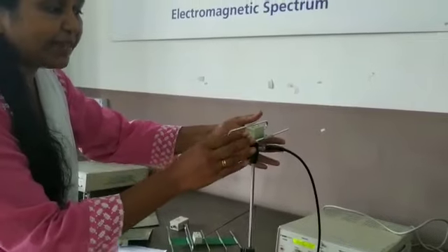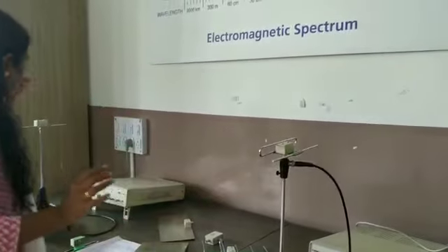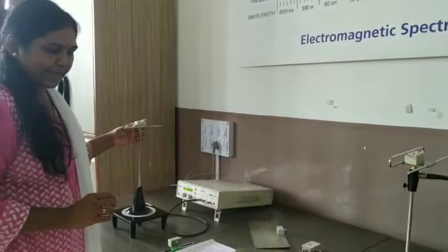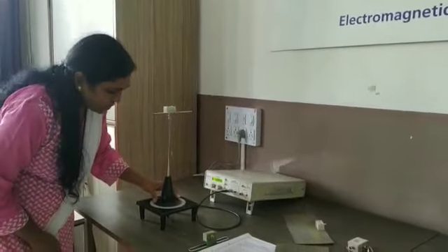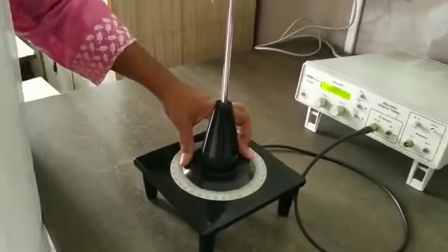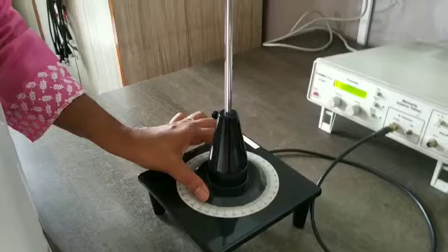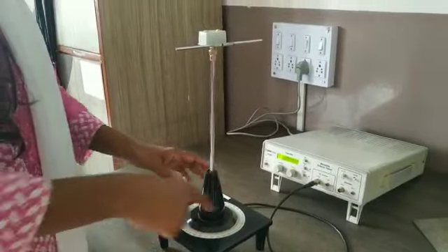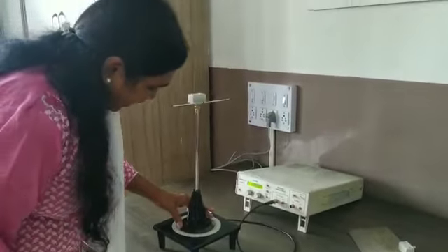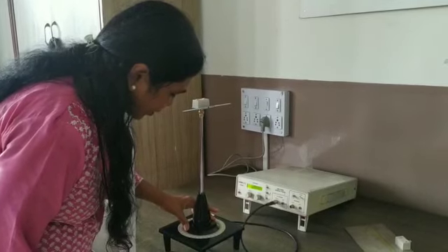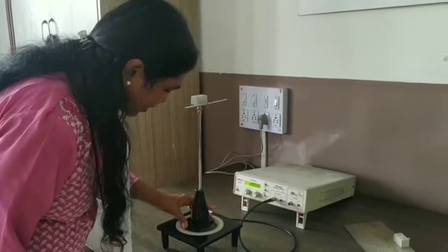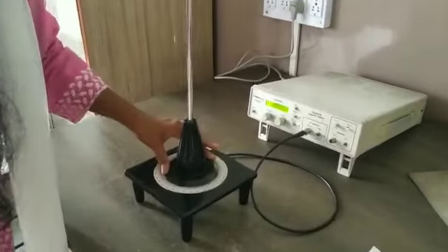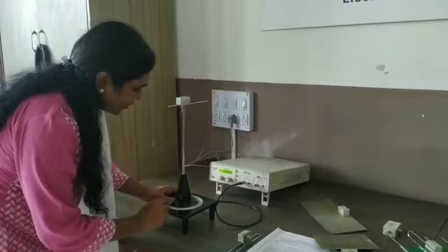And this antenna is a common antenna, which will act as a receiving antenna, and this, our test antenna, will act as a transmitting antenna. Here you can rotate the position of the antenna from 0 degrees to 360 degrees, and you can take the readings for each angle. You can vary the antenna position like from 0, then 10, 20 like this, and you can measure the received power at the receiver. Now at this moment the position of